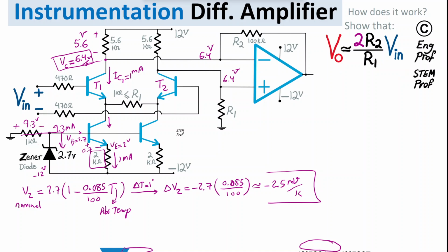Okay, so what happens now when we have some non-zero value? For example, when we connect some voltage between these two nodes. Let's see what happens. As a result, there is a bias, an I base current, flowing through the base of transistor T1. It's important to make sure that we're talking about matching bipolar junction transistors here. So T1 and T2 should be matched transistors so that they are on the same substrate, in the same package, and they benefit from the same junction properties and thermal properties. So basically they have the same saturation current.